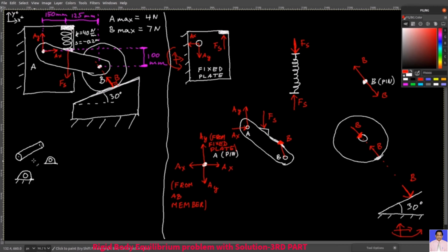Your pin here, let's say that it has a force F here, and then here and here you have F over 2 and F over 2, and then due to Newton's third law, you have the opposite F over 2 forces in this direction, and so you have this distance d over 2 meters here and d over 2 meters here. So all the forces and moments are balanced out here. So in the world of statics, everything is fine.